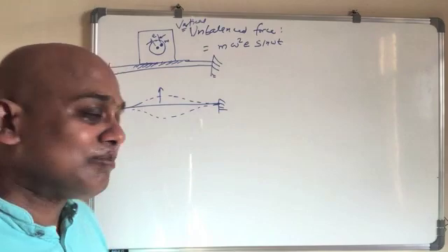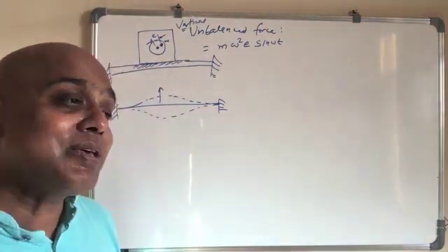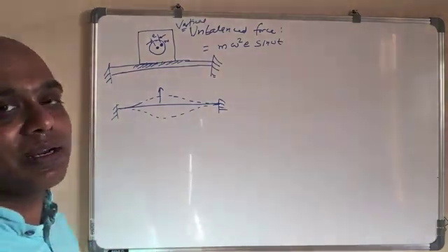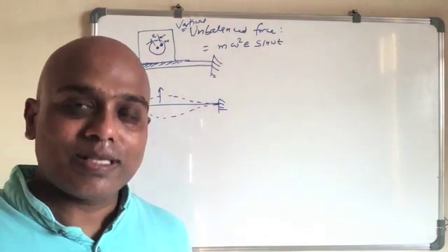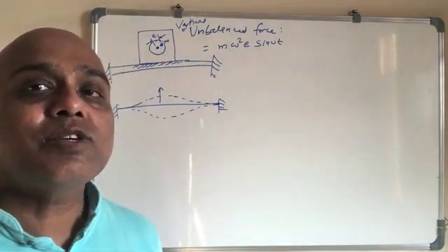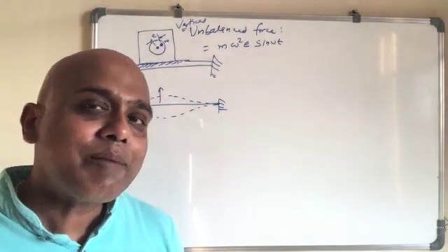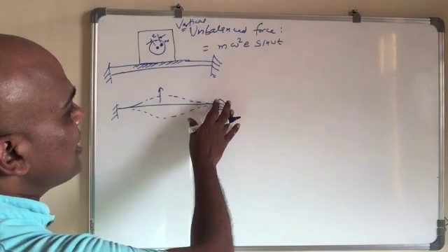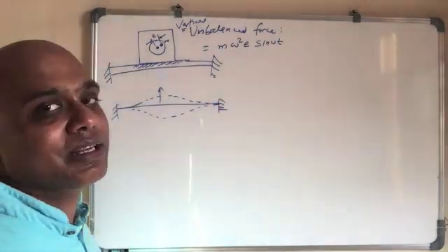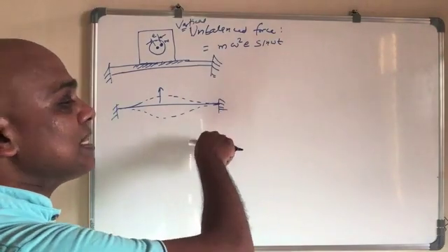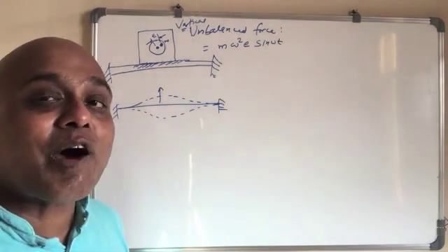That means if you increase the angular velocity, you will see the frequency of excitation also increases, and we have seen that somewhere there may be resonance, and because of that you have seen that at resonance the displacement is very high, so it is going to vibrate quite a lot, and because of that there will be a problem. The structure can be damaged actually. Yes, there will be material failure. The stresses may increase so much that it may be more than the allowable limit.